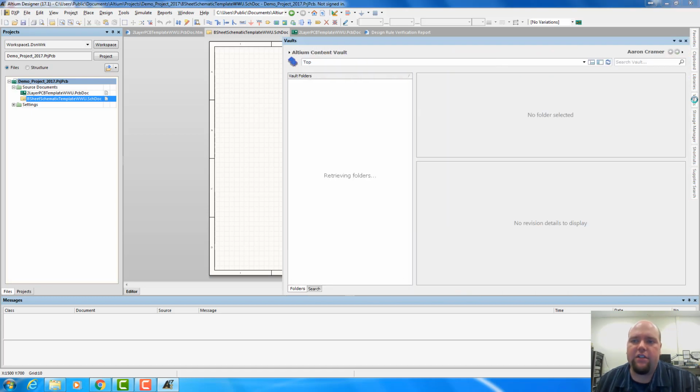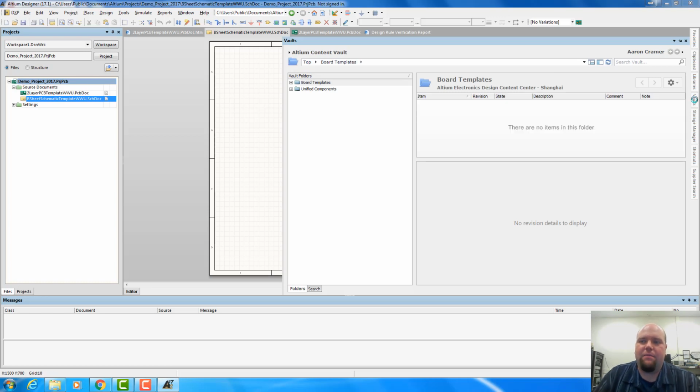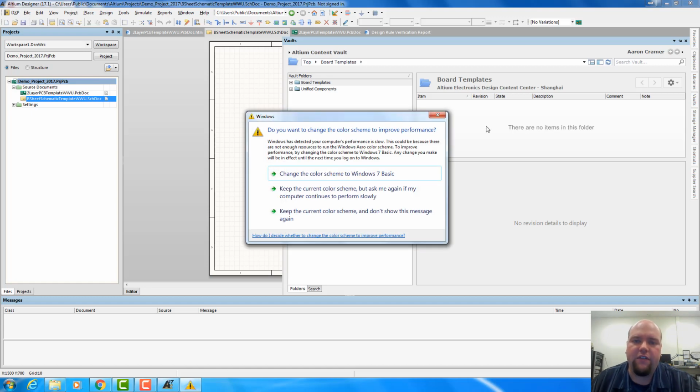The neat thing about vaults is they're a way to rigidly structure managing resources. So in the case of a vault, you can have one centralized location where you store all these components. If you're working for a company and you have dozens of people accessing the same components, it lets people make changes to components, update different versions of a component, and it allows everybody using that component to have some control over: do I use the updated version? Do I roll back to a previous version of the component? And so it's a better form of managing parts when you have lots of people working on the same thing.